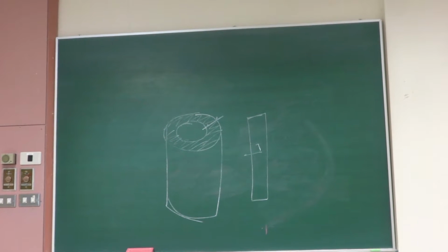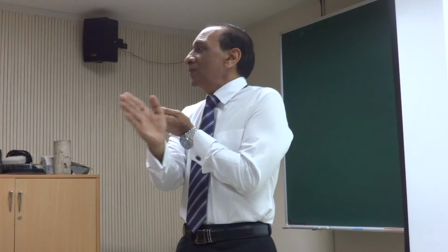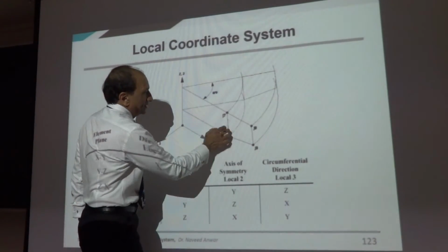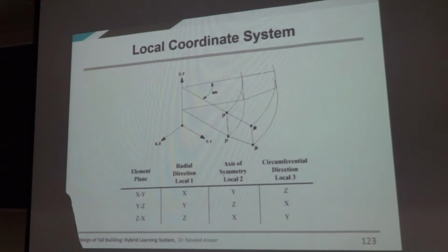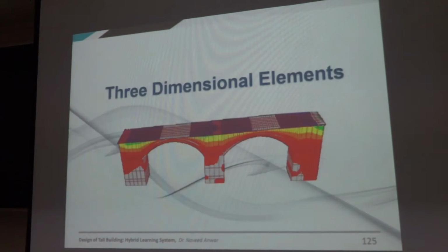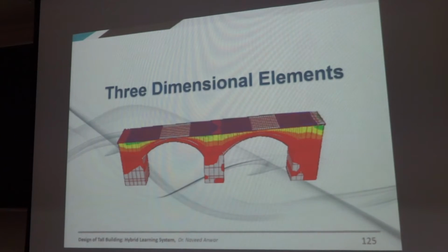That's it. I do not need to model all the sections because the stress in all the sections, or let's say pressure inside, is going to be the same. I do not need to model all the sections and create a solid mesh out of this one. So I just need to model one plane, plus saying that this is symmetrical about some axis. It is just like membrane, only it has this tendency that you have this element and it goes around some axis with an angle theta. So it's a semi-solid element with only one plus property about the symmetry axis. So just only know that, because we are not going to use it in problems. If it was a finite element course, I would tell you more about it.